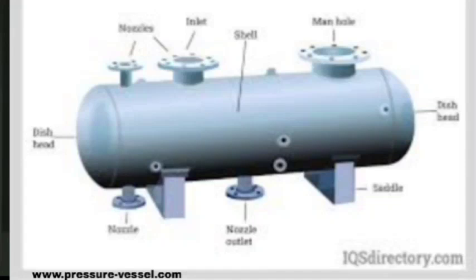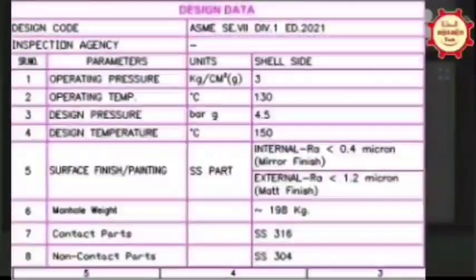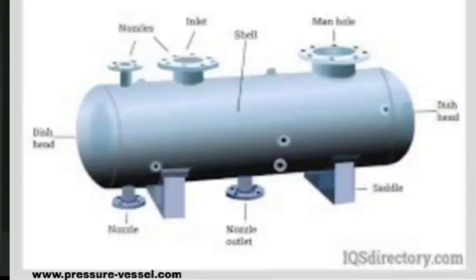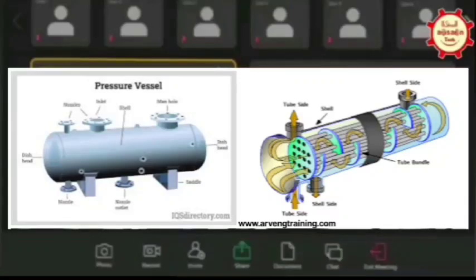Balakrishna, the process design team will do the sizing of the vessel: how much diameter, how much length, what the process parameters and design conditions should be. They decide based on their process requirement and give you the size. That is process design. But as far as we are concerned, we have to do the mechanical design of the vessel. As Ravi told, we need to check the structural integrity of pressure vessels, heat exchangers or any similar equipment for the given loadings.